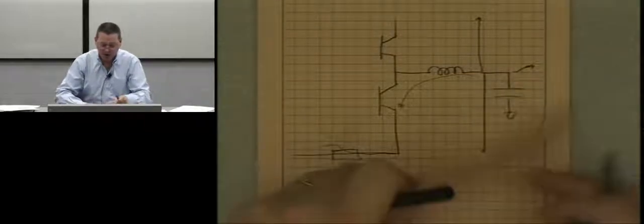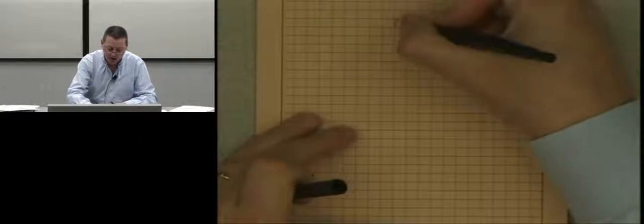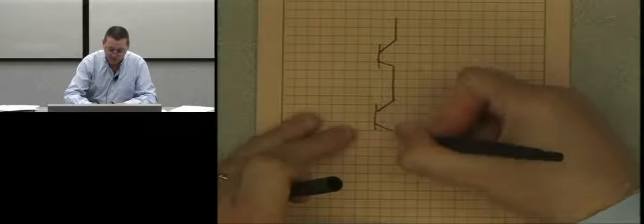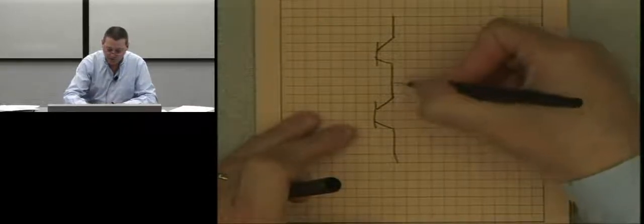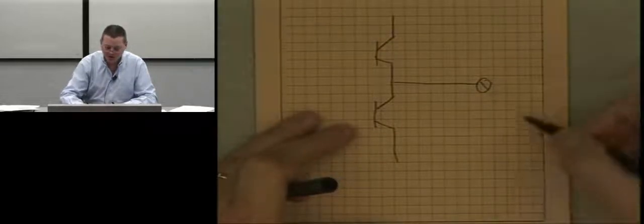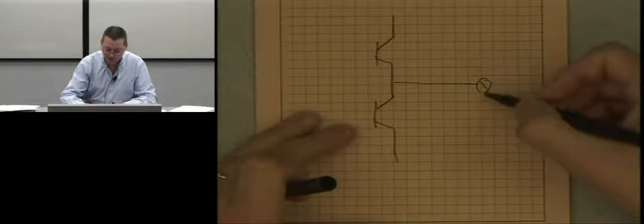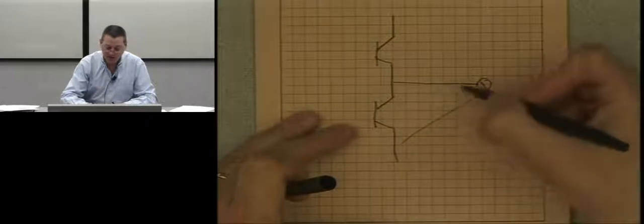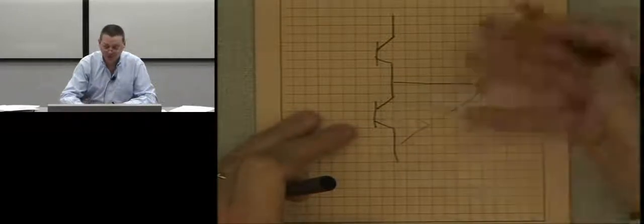But in the case of a motor drive, typically the inductor is the motor, right? And so on the drive, there's no inductor. This goes to the outside world to a big screw terminal that someone can misapply and get a screwdriver across. And so you can end up with a short either to negative bus or positive bus or earth. But the thing is, there's no inductor here. So when you turn the device on, as fast as it turns on, you're going to have current immediately through the device, a fault current.